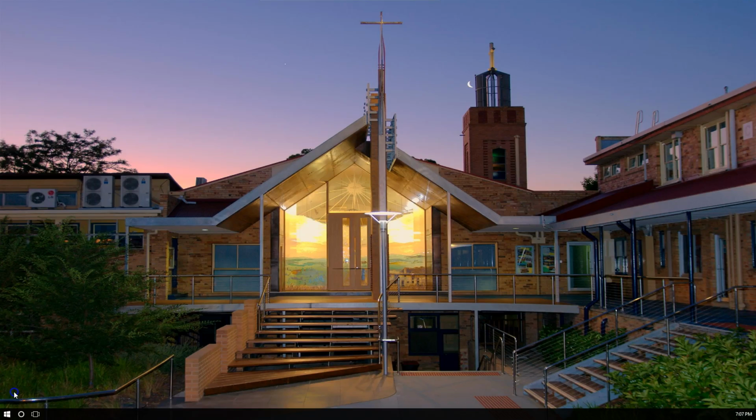The robot, depending on the light reading, will move smoothly like this. Our table would look something like this. At the furthest end, this becomes better. Too far off the line, the robot will turn more sharply to get back onto the line. However, at the middle, this will cause more oscillation. The bigger the number, the faster the wiggle.